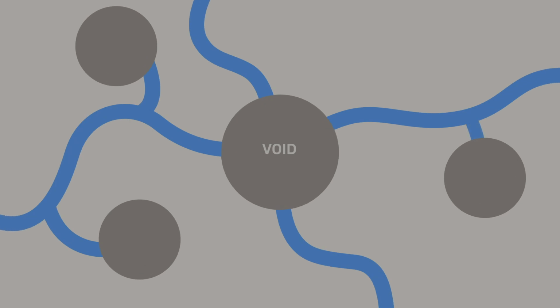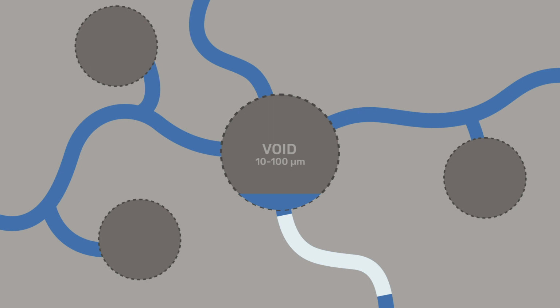This is done by using surfactants to create air voids 10 to 100 microns in diameter, surrounded by a thin shell of cementitious paste with a fine porosity. These air voids serve as sinks for water displaced by ice formed in the small pores of the cement paste.